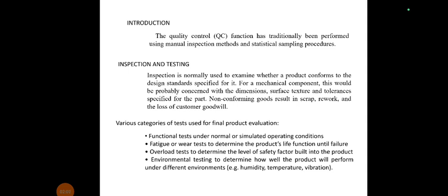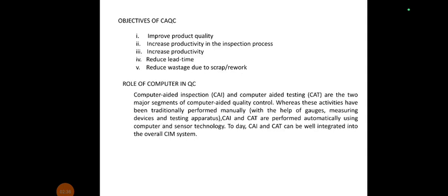So next one, there is another aspect of the traditional quality control inspection process which detracts from its usefulness. It is often performed in such a way that measurements are taken and the quality is determined after the parts are already made. If the parts are defective, they must be scrapped or reworked at a cost which is often greater than their original manufacturing cost.